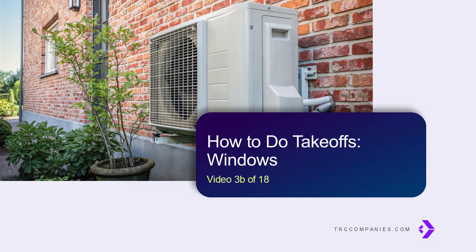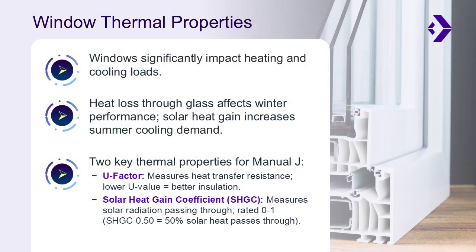Today, we're going to focus on how to do takeoffs, windows. Let's dive right in. Let's start with the basics. Windows can be a significant contributor to both heating and cooling loads. Heat loss through glass can affect the home's winter performance, while solar heat gain increases cooling demand in the summer months. Understanding a window's thermal properties and having accurate window inputs are essential to sizing heat pump equipment appropriately.